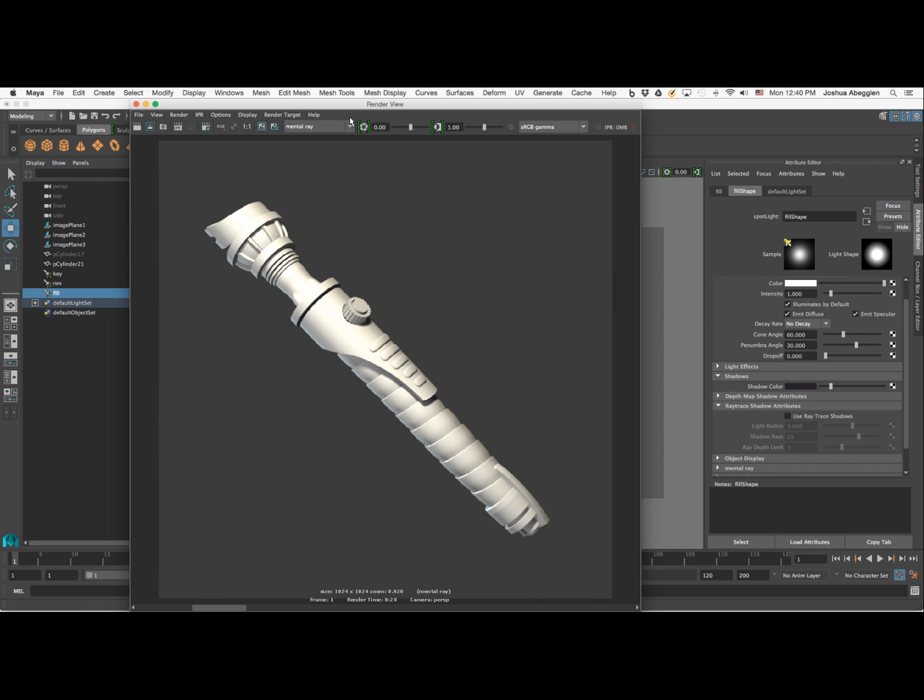Okay, there we go. When I said pause this one, I meant pause the screen capture while this render occurred. Now you can see, I'm going to go ahead and save this. Scrubbing back and forth between just the two lights and the third light, that third light is really kind of blowing things out. It's way too intense with that intensity of 1. I'm actually going to try and set this at a much lower intensity, maybe a 0.25, and see how this looks.